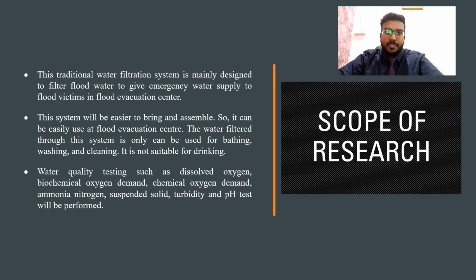This system will be easier to bring and assemble, so it can be easily used at flood evacuation centers. The water filtered through the system can only be used for bathing, washing and cleaning. It is not suitable for drinking. Water quality testing such as dissolved oxygen, biochemical oxygen demand, chemical oxygen demand, ammonia nitrogen, suspended solid, turbidity and pH test will be performed.